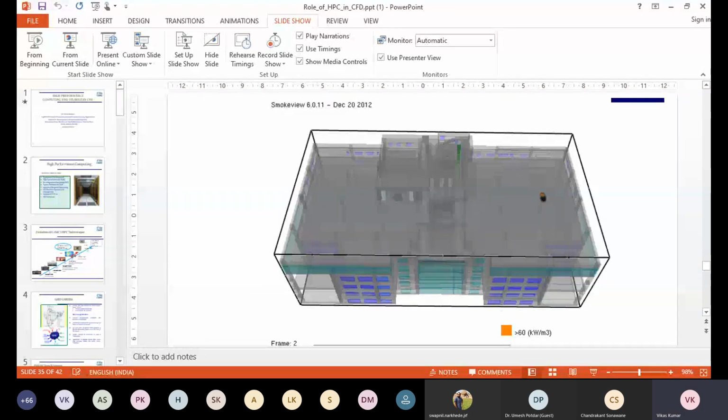Okay, so in CFD, the academic people, you people, can work on two fronts. Either you can use the OpenFOAM CFD tool as a base and deploy its parallel version, and solve some large size problems. That could be one approach. The other approach is that you can identify some of the linear algebra libraries in OpenFOAM, which has different solvers like icoFoam and simpleFoam. You can change the libraries, optimize the library, and then see how you get the speed up. Further, you can explore different kinds of schemes. If you want, you can add different numerical schemes also. So these are the research work that you can take up using OpenFOAM on the HPC platform.